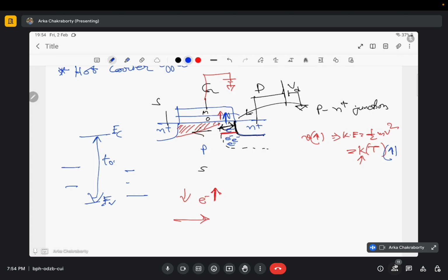In a p type device, the electrons coming into this channel might get enough energy to jump into the TOX (or holes, if it was n type). This electron might get lodged in the TOX, causing damage to my oxide.